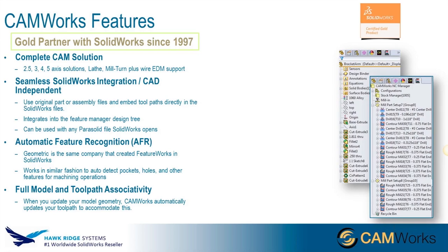But you don't necessarily need that data if you're a job shop and you're working off imported files such as Parasolid files or STEP files or IGES files or those kinds of things. You can actually bring that information in too, and the feature recognition will actually look at it and start extracting the data from the model as well.